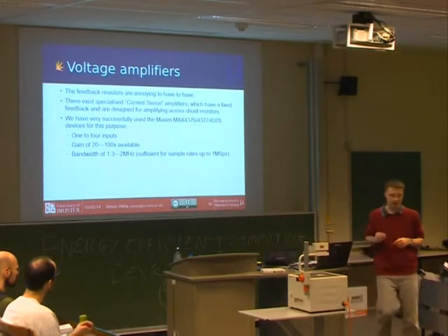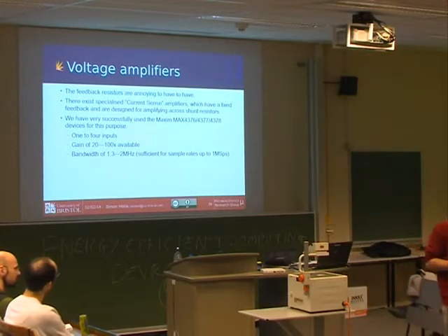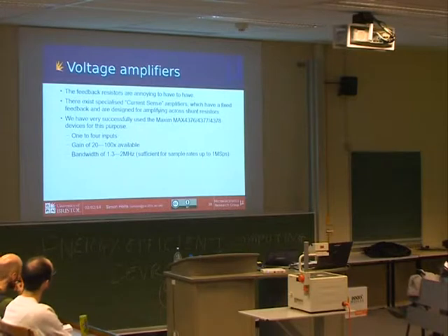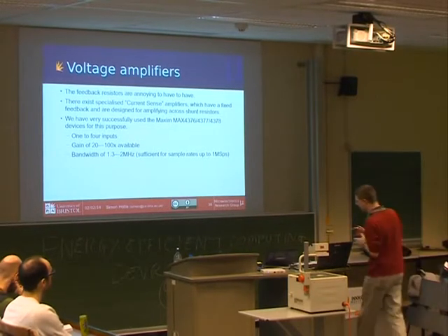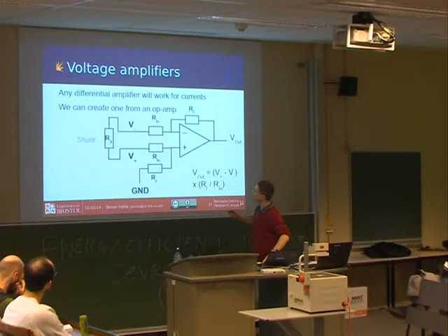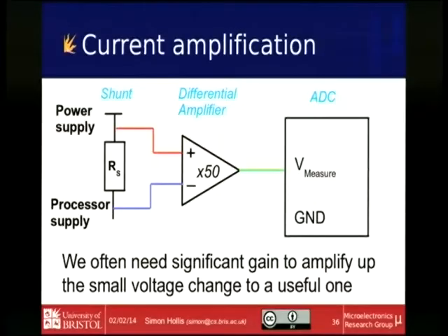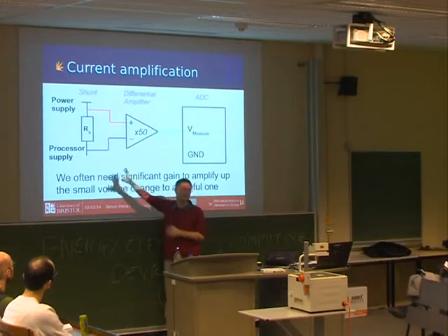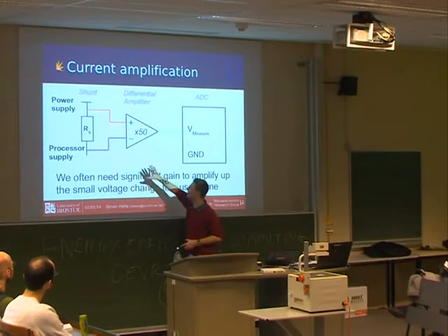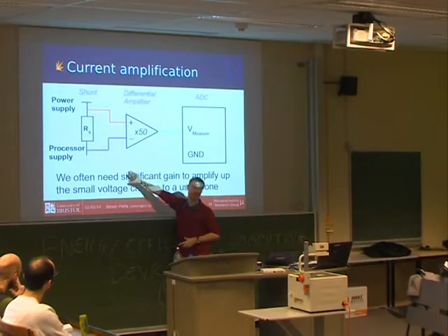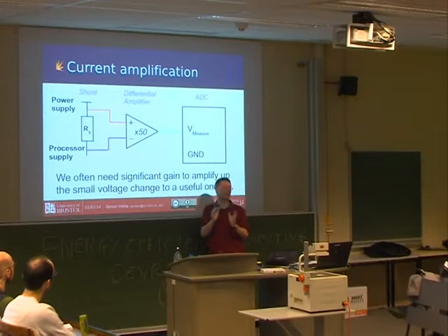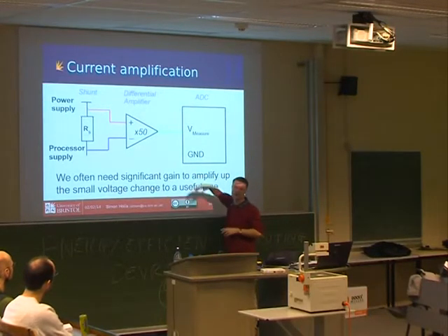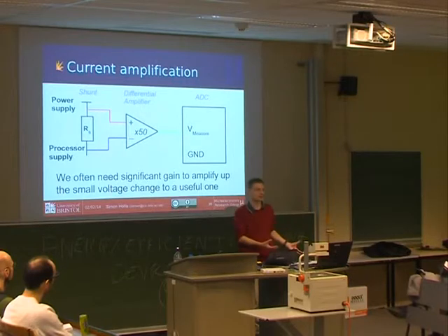There's no point in there? There's not quite no point, there's little point in that, because what you've done is you've created a system where... go back to this diagram. So you've got a system here. If this can measure very, very quickly, you've introduced in the middle a weak link. Okay. So this passes all of the information from the resistor into the ADC, but it has this limit. And so the ADC can go faster and faster, but there's no more information to be got.